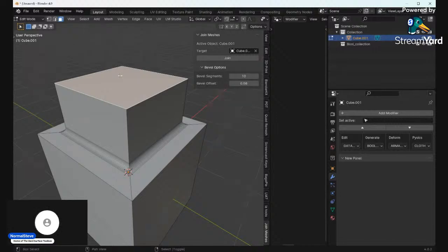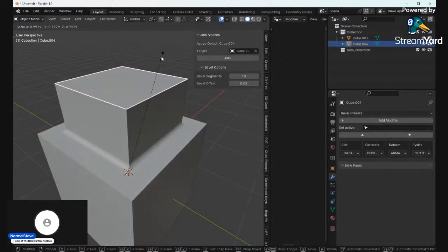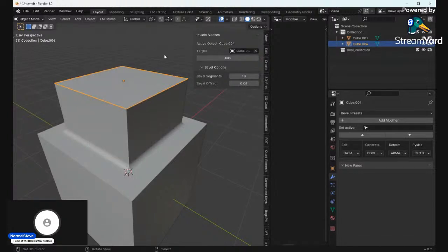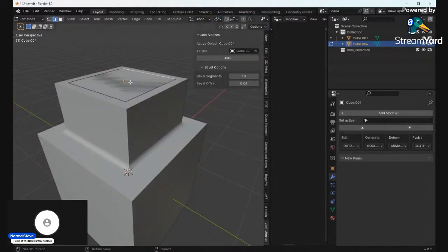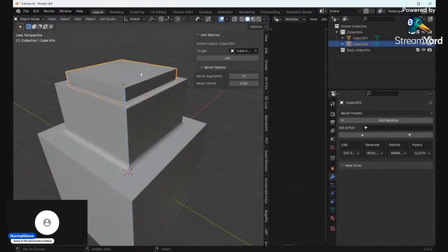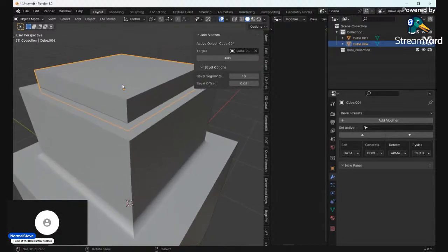And you can also, like, Shift D a copy of something. So if you're working with like a panel, you could just separate this by selection, and I could just fix this up, origin to geometry, maybe scale it a touch. And the general idea is that this is going to be maybe slightly buried in the mesh, because you don't even have to snap with this.